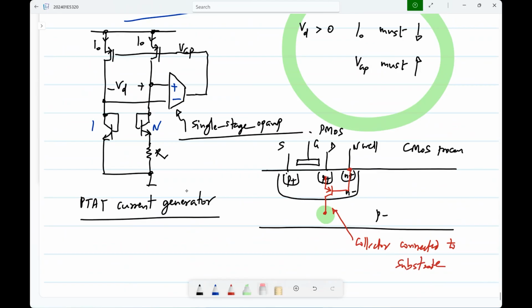Now, what aspect of the bipolar transistor's physical structure makes beta high? The bipolar transistor has, in this case, P, N, and P regions: emitter, base, and collector. Which aspect strongly influences beta? The base. It should be thin. If it is very thick, it's like having two separate diodes, right? What is the difference between a bipolar transistor and two diodes?